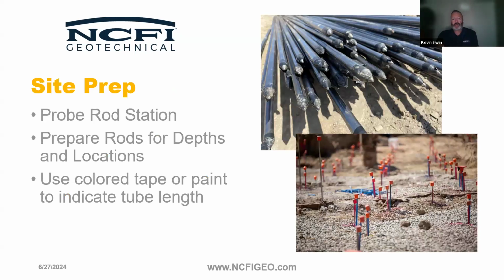So operations, site prep. First thing, when getting on site, of course, we're going to take pre-elevations. I want to make sure that I know exactly where everything is before I start. But one of the main things that you're going to have to think about with site prep with deep injection is the drilling, driving, and probe rod preparation that you're going to have to do.